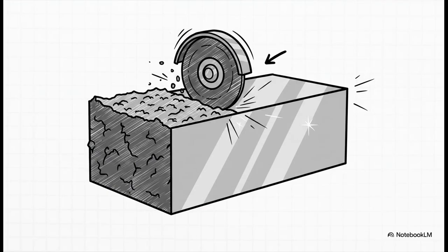The reality of sand casting is that the surface finish it leaves behind is generally, well, quite rough. If a part needs to fit perfectly into a machine or have a smooth, dimensionally accurate surface, it has to be machined down after it's cast. But think about it. If we made the pattern to the exact final size, the moment we grind it smooth, the part becomes too small. So we apply what's called a machining allowance. We make the pattern even larger, intentionally adding extra sacrificial metal that we are fully planning to shave away later.